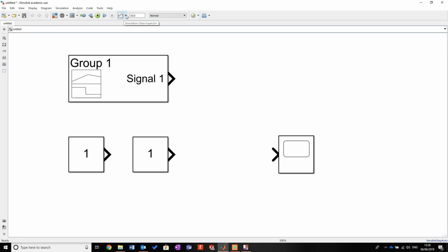Simulink Data Inspector. Now, when you're running something big, a massive simulation, let's say you're looking at a wind turbine and its efficiency over 20 days. When I ran my KTM 550, I ran the simulation looking at the running-in procedure. It needed to run for an hour, and I wanted to look at different variations occurring when, say, RPM was basically the load or the angle of the throttle body, just to see what effect it would have on compression ring dynamics.